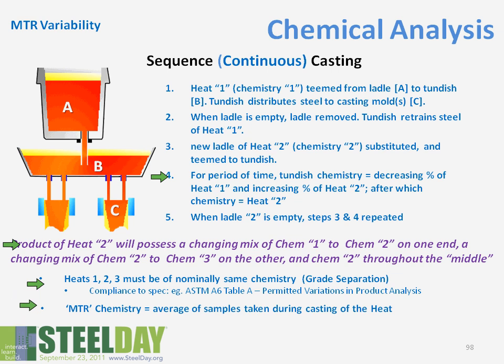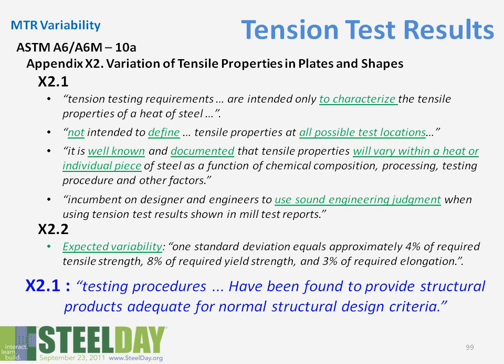Essentially what you're going to see in the mill test report is, as a steelmaker, we're going to be sampling this throughout the casting process, and you're going to get an average of that chemistry. So yes, there will be variation in chemical results if you do a product check on your mill test report.